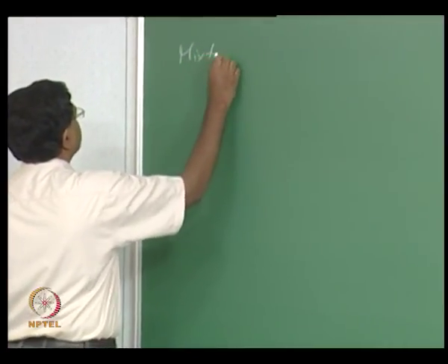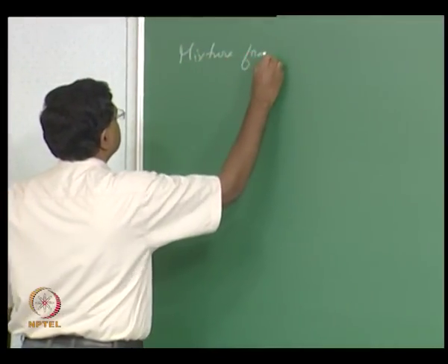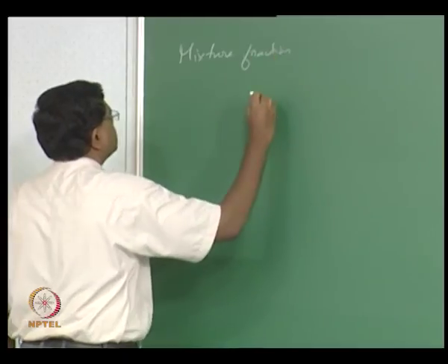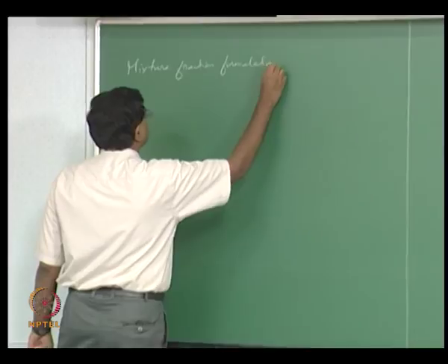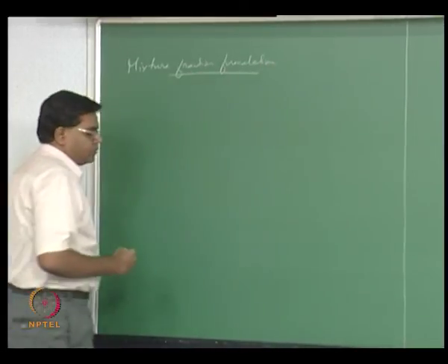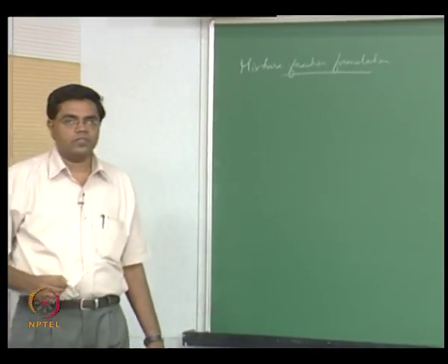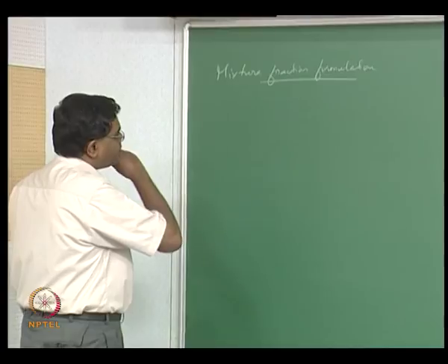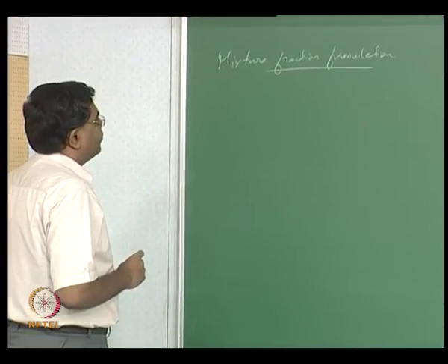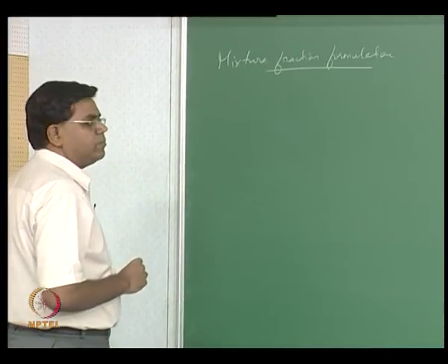Adopt what is called the mixture fraction formulation in trying to describe diffusion flames. This is actually a powerful idea for combustion in general, and with particular context of diffusion flames and partially premixed flames.